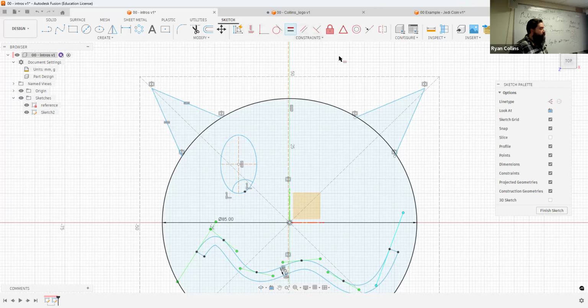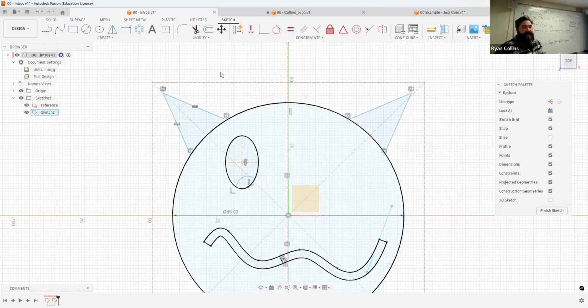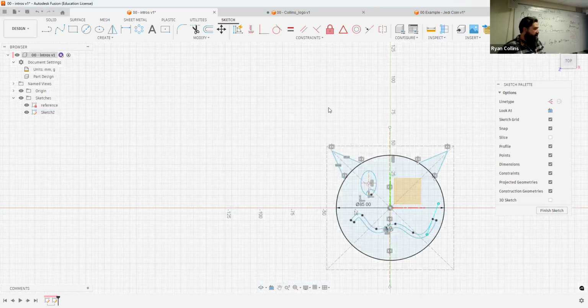There's a bunch of these, and we'll go over them in time, but just know that this is how you can affect your drawing to make certain things match. I'm just going to draw this off to the side. You don't have to do this. But let's say I was trying to make a box. We're using the box tools, but let's just say, bink, bink, bink, I don't really care. I'm trying to make this a box. Well, that's a pretty god-awful box. But with constraints, I can make this whole thing match.